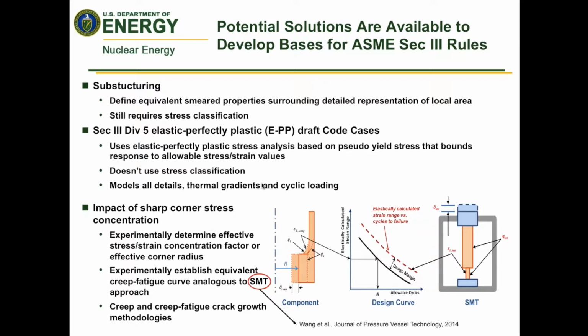These allow a design margin to be put on the SN curve from relatively simple laboratory specimens that approximate the kind of design features that one would see as variable sections in actual vessels.